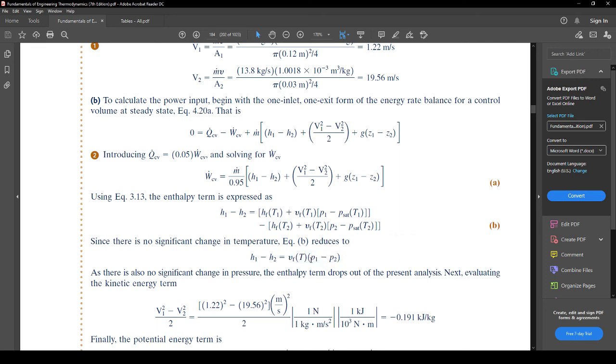It's the pressure after minus the pressure before, right? And then it's multiplied by the V sub f term. And what V sub f would be, it would be at state 1. So it would be this volume value at this temperature. And this gives you the perfect pump equation. So basically work can be rewritten as this.